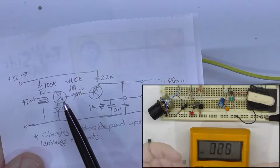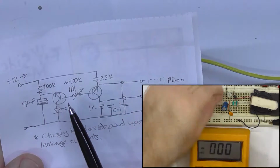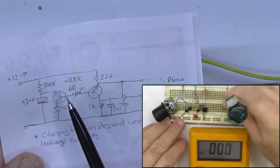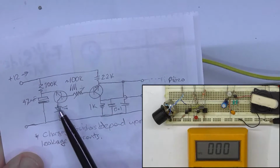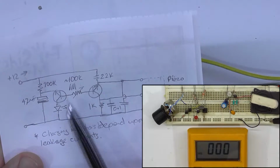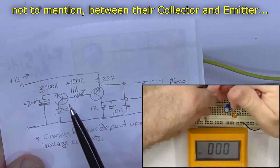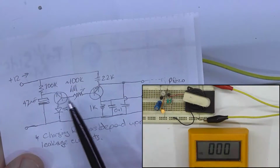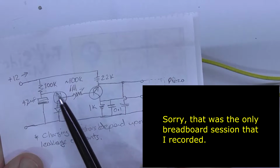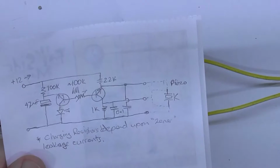And many transistors are that low, including some very high voltage transistors. They are high voltage between the collector and base, but 5, 6, 7. I think one I'm going to test later has got 9 volts between the base and emitter, and yet it has a 700 volt range on the collector to base.